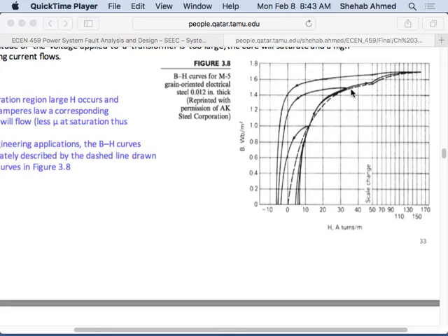So the next time you energize the material or run the transformer, you're not necessarily starting from B equals 0 in the core. There may be some residual flux, like a magnet. Magnets have some residual flux. If you remember in 322, the coercive force or something, I'm not sure what it's called, but there is some residual magnetism in the magnet. After you magnetize it, it is not demagnetized. It will maintain its magnetism.